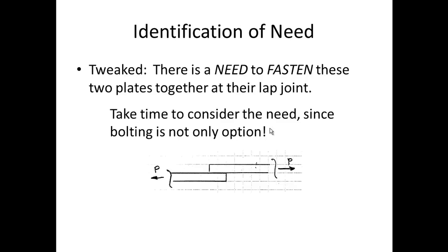Let's think of the need in a slightly different way. Instead of saying bolt, let's say there's a need to fasten these 2 plates together at their lap joint. This is a tremendously different need and opens up a whole lot of other possibilities, since bolting is not the only option you have. You could weld or epoxy these plates together.